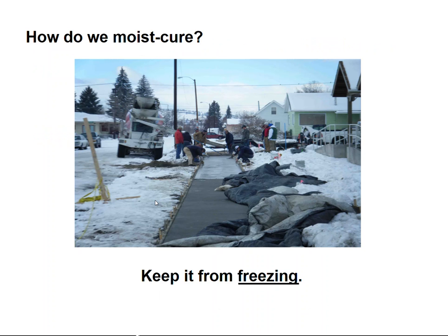Another way is to keep your water from freezing. So if you pour concrete in the wintertime, that water wants to freeze just like the snow and the ice and the puddles. So the second water freezes, it's no longer liquid water anymore, and that also denies it the ability to contribute to the hydration process in concrete. So you have to keep water present, but you also have to keep water liquid. So you can use insulating blankets, and this was a sidewalk we poured in Butte a couple summers ago as part of a class project for some habitat homes.